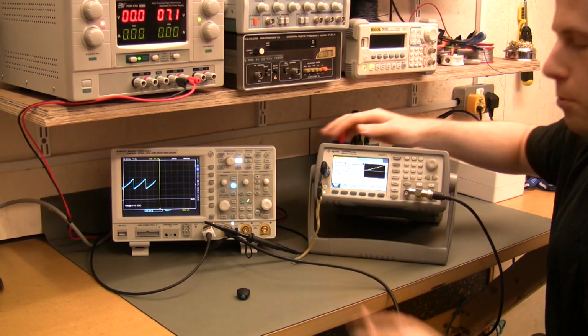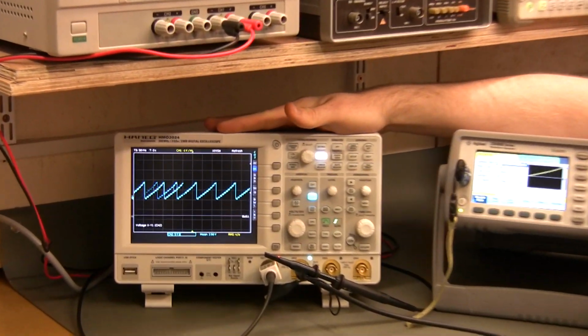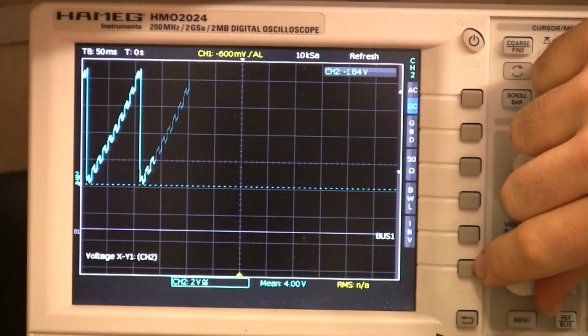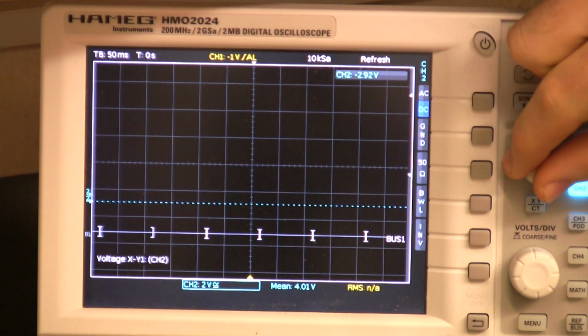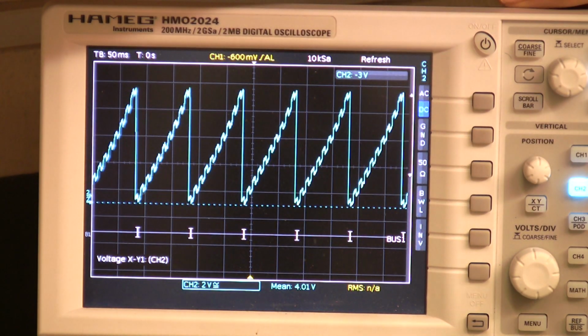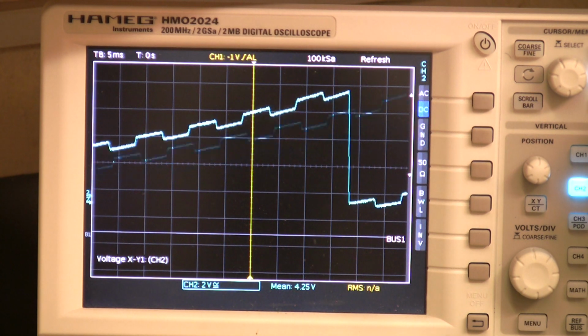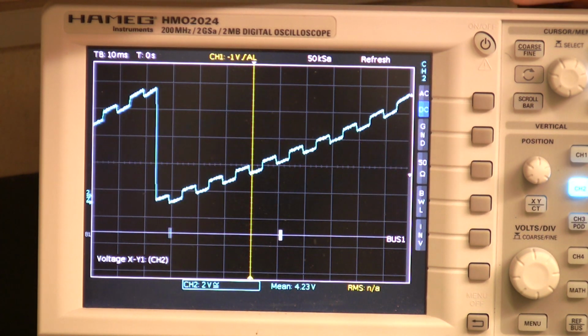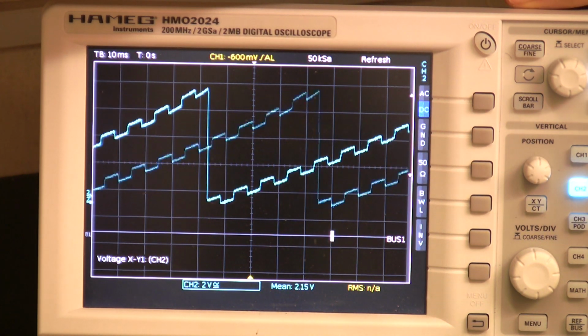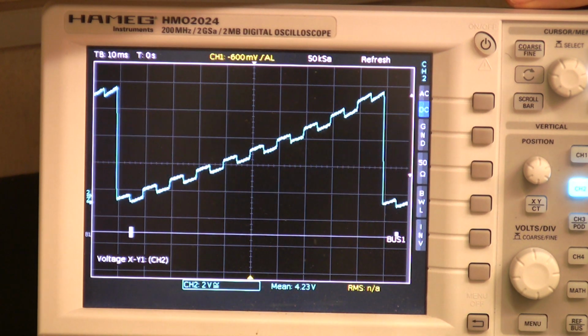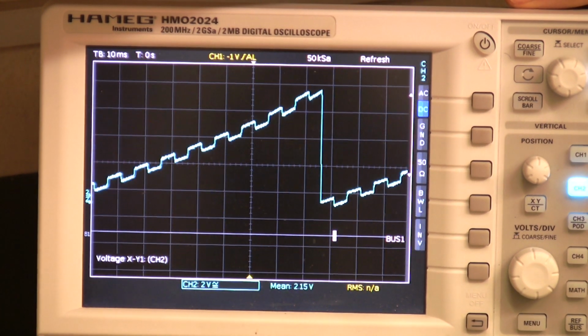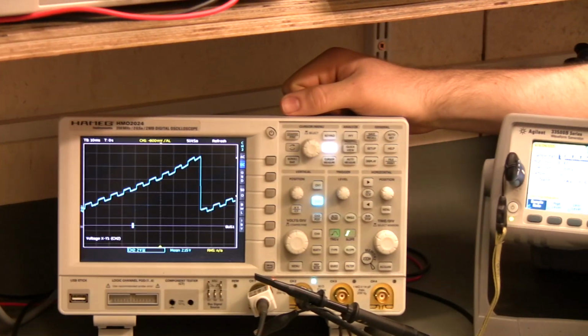There we are, having got a sensible sample rate up, you can see that the waveform has now completely appeared on the oscilloscope. And it may make it look difficult, but it's actually a very straightforward process there. So like I say, that's 5 minutes of editing data in Excel, save as a CSV, import it, done.